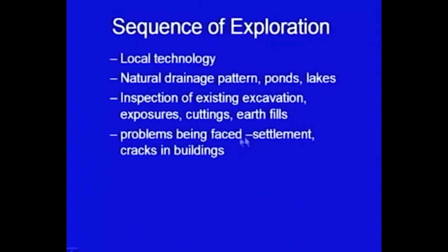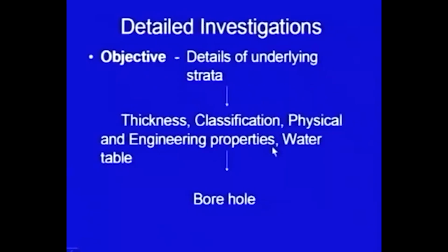And also you look at the buildings, if there are cracks in the buildings because of some foundation problems, if there are excessive settlements, they also speak of some problems. So, they also speak about the subsoil strata. All these things you should get when you visit the site. So, visiting the site helps us in a big way, you get lot of information from that.